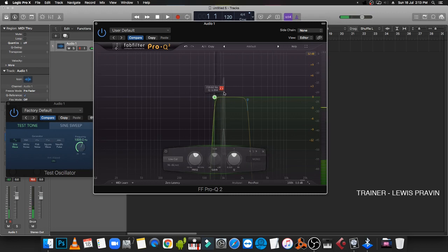So move this to a level that you don't actually see anything above minus 50 on the graph. So this is exactly minus 45, minus 50, minus 55, minus 60. So make sure you don't filter anything above minus 50 or minus 45 always. So let me keep my filter here.